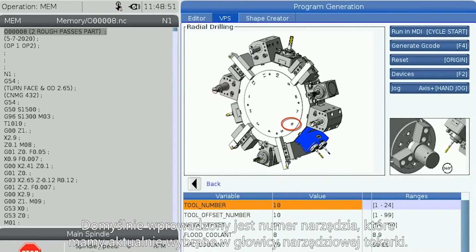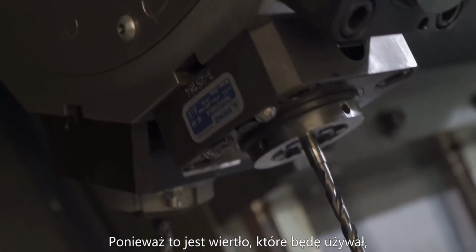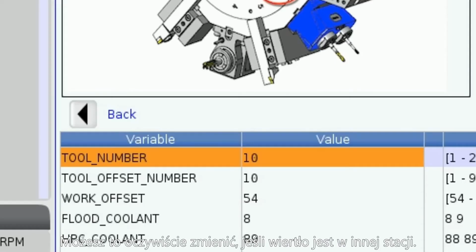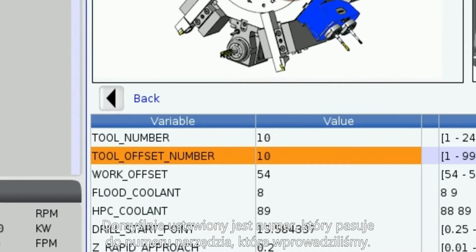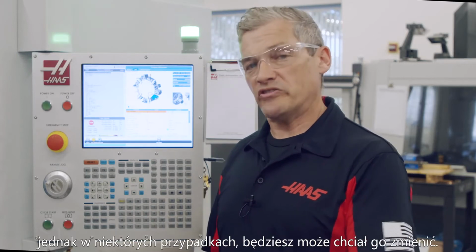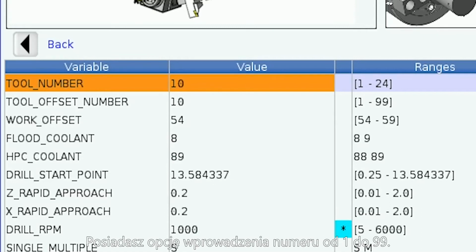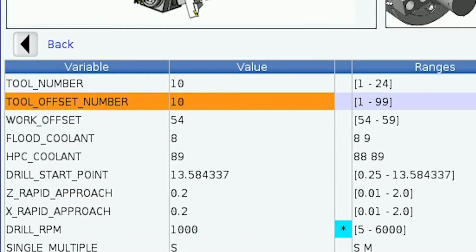This defaults to the tool number already in the cutting position on the lathe. And since this is the drill I'll be using, I'll leave this set to 10. You can change this, of course, if the drill is at a different station. The next variable is the tool offset number. This defaults to the number that matches the tool number we just entered. Having an offset number that matches the tool number is good practice when programming, but in some cases you might want to change it. You have the option to choose any number from 1 to 99. For now, I'll leave them matching.